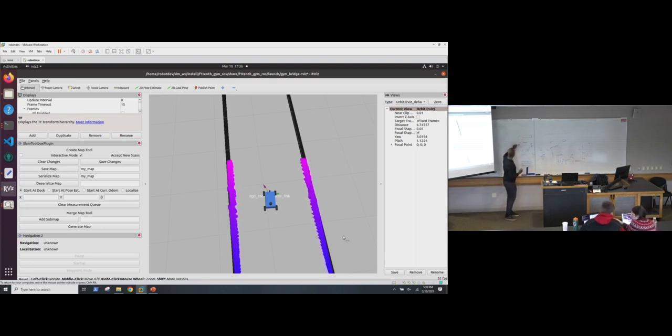But I try to break it down as much as I can. If there's a straight path, I might just go here and then have it come here or something. But you have to figure out that increment, the task it needs to do, because it can start deviating and it depends on the noise in the system. So that's one of the things you will have to figure out through experimentation: how many goals you really need to get along the path after you get a map. That's just trying it out. It won't run into a wall because it will see an obstacle, but if it starts to zigzag like that, then you might want to give it a little bit more help. It's going to get there, but it's going to take forever. Right. Yeah.